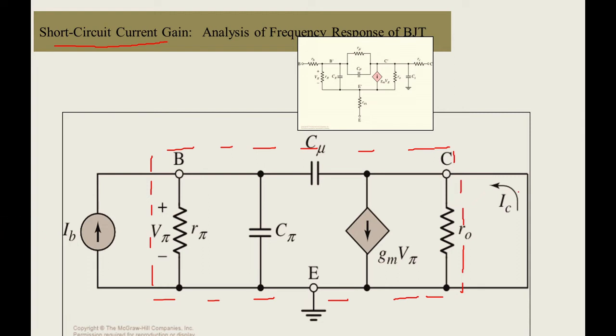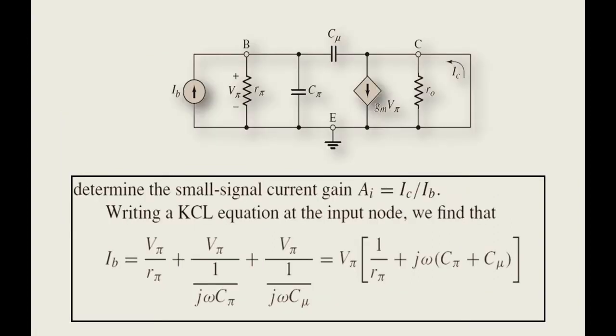While you short circuit this load, this R naught will be negligible because there is no resistance in this short circuit part, and you have a high resistance in R naught. So current will not go to this path. Current will go only through the less resistance part. In that consideration, I remove it from this equivalent model. So for further analysis, you need not take this R naught. R naught will be removed.